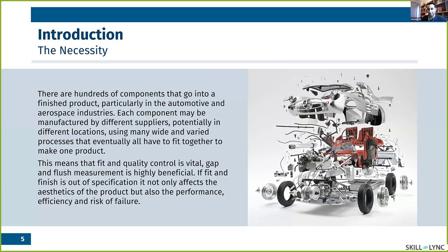The negative value of the flushness. So that if after thousands of times opening and closing, something happened, it couldn't be observed, and it couldn't cause a problem with the appearance of the car. So gap and flushness are really vital and essential to be considered during vehicle design.